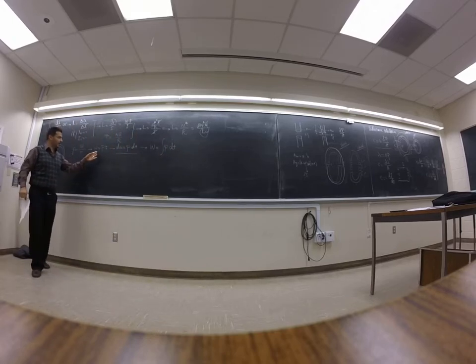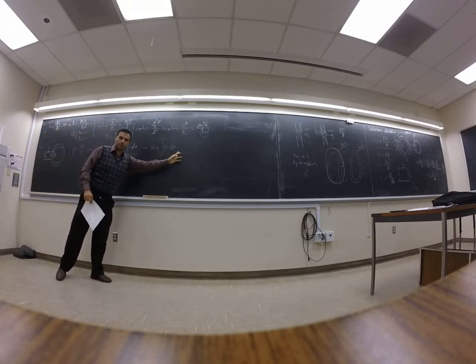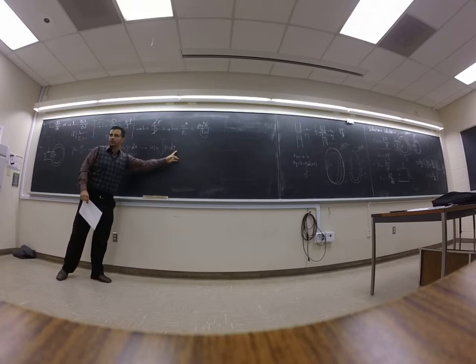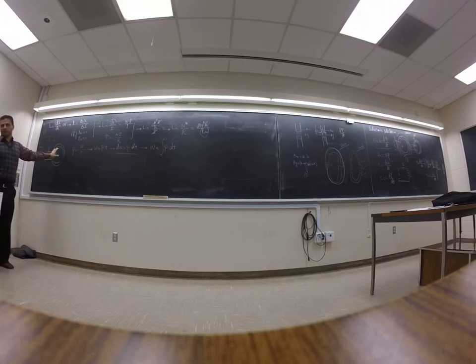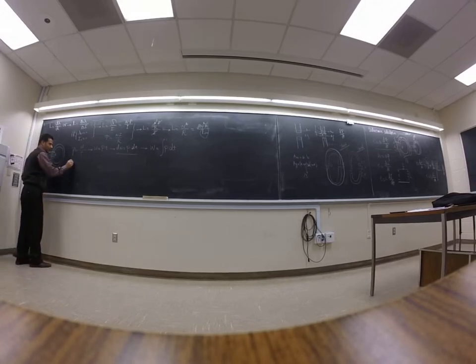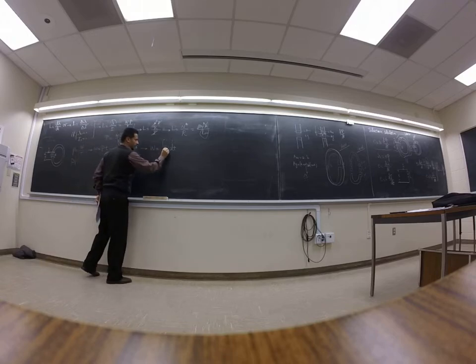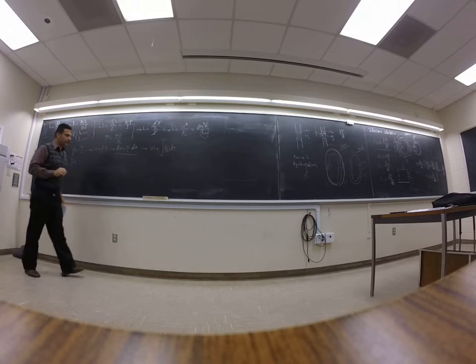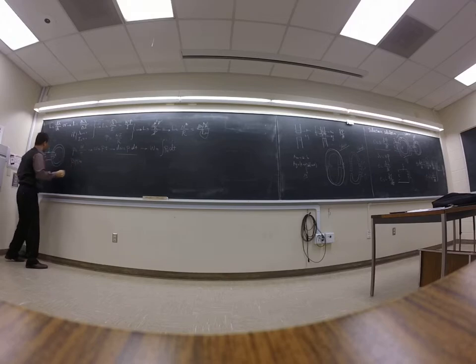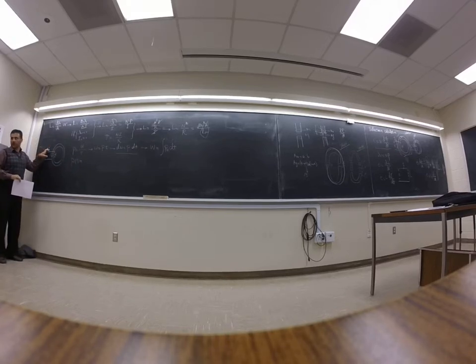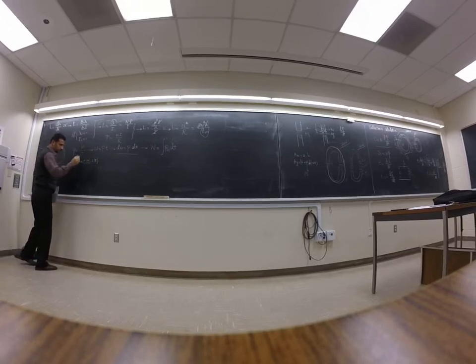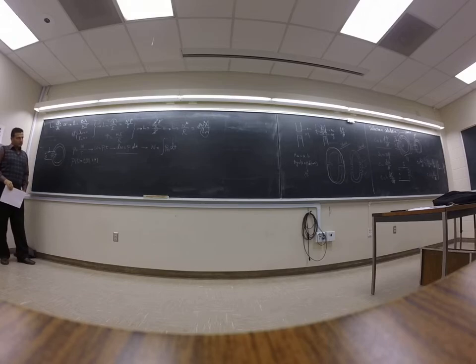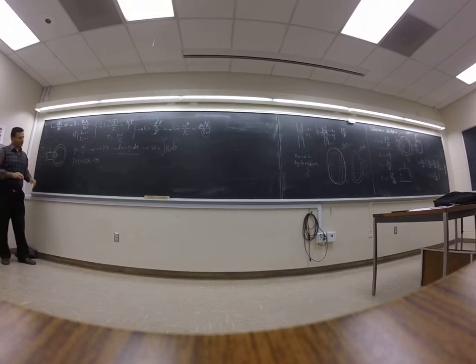So if power is constant, it's easy. You use this equation. But when the power is variable, it changes with time, so you use this equation. Now I'm going to use this equation to calculate the energy stored in this inductor. So what is power? Instantaneous power. This is the instantaneous power, p(t). What is p(t)? That's the voltage times current, right? e(t) i(t). We can replace it over there.